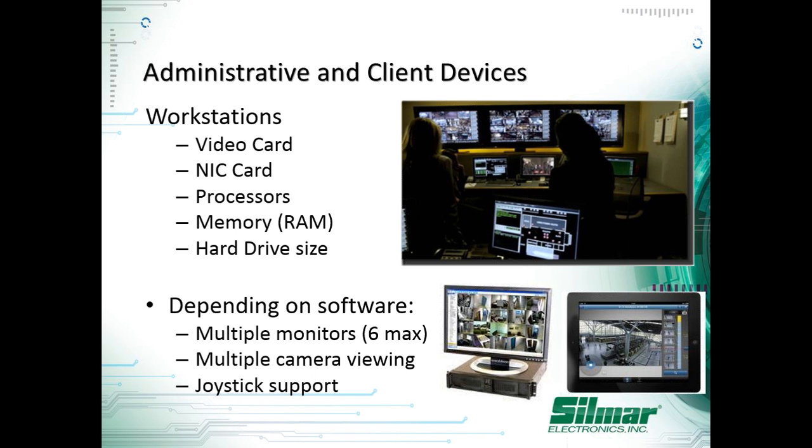So how do you select a recording device? A lot of things go into selecting a recording device. Things like, what kind of integration is a customer looking at? How many clients are going to be connecting to the system? How many sites are going to be using the system? What cameras does he have? Is the NVR compatible with the cameras that are existing there? Or the camera that he needs in that specific situation, is it compatible with a certain VMS? These are all things that need to be taken into consideration when building systems, and we can help you with this as well.